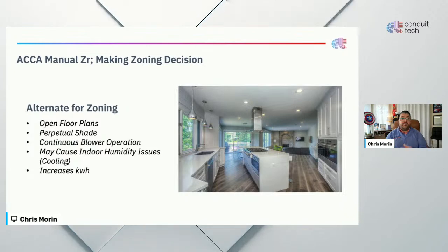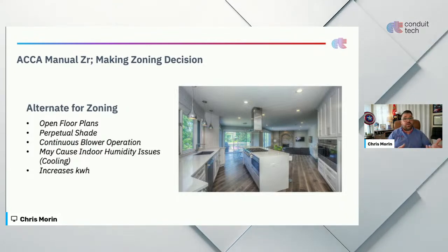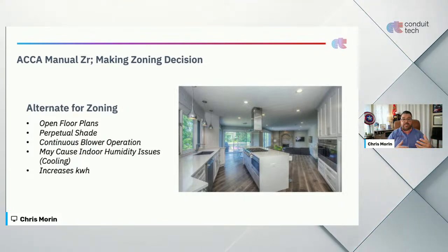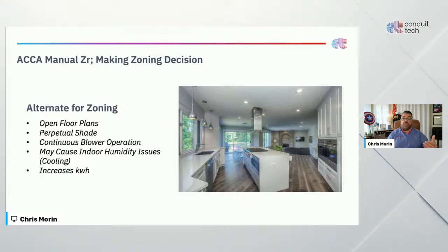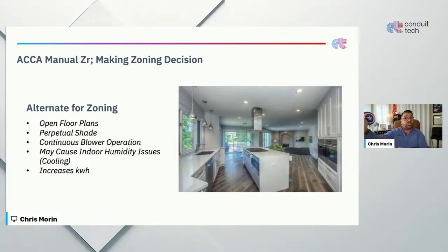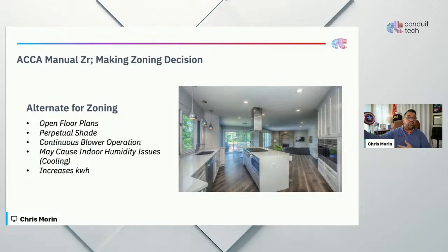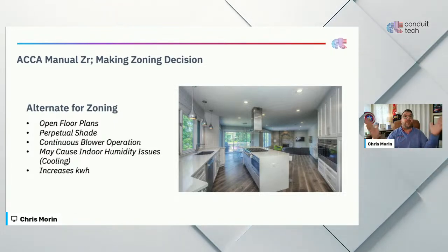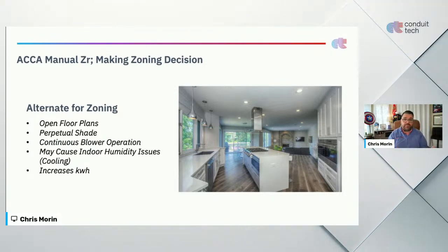Also, you can find that if you're unable to zone certain areas that have, let's say, skylights, a better option, instead of trying to zone that because it doesn't meet the homeowner's budget, maybe to get the homeowner to put shades on those skylights. That could drastically drop the gains, and it's more compatible with those other rooms now.